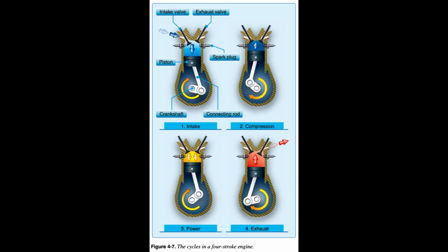Four-stroke engines are very common in most aircraft categories and are becoming more common in WSC aircraft. Figure 4-7. Four-stroke engines have a number of advantages, including reliability, fuel economy, longer engine life, and higher horsepower ranges. These advantages are countered by a higher acquisition cost, lower power-to-weight ratios, and a higher overall weight. The increased weight and cost are the result of additional components, e.g., camshaft, valves, and a complex head to house the valve train, incorporated in a four-stroke engine.